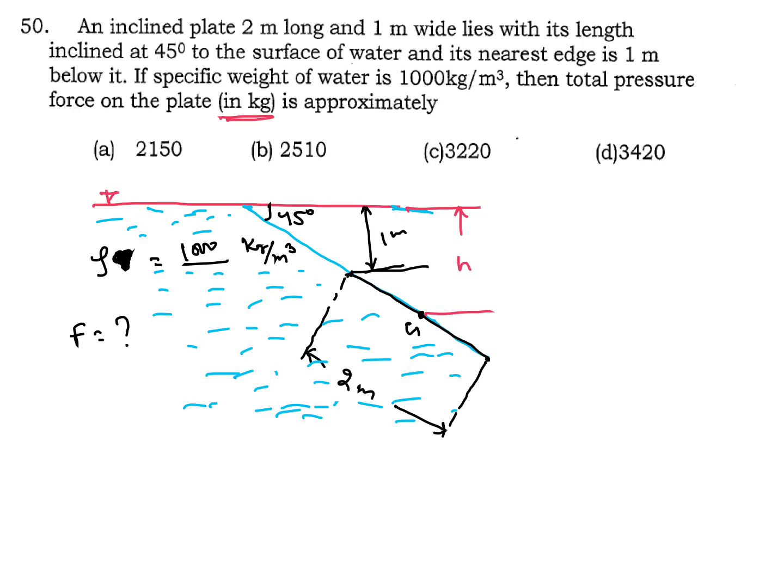We know force equal to rho g A h bar. Here in kg, so rho A h bar. H bar is, this distance is 1 meter. One plus 1 into sine 45 degree.